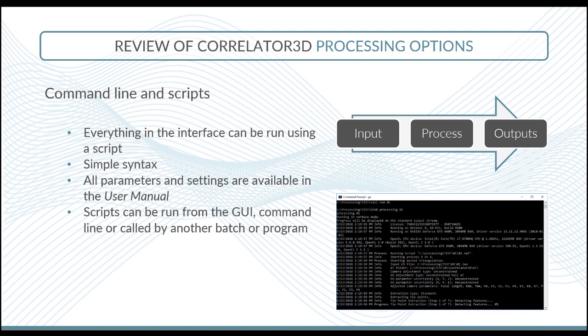So this makes a very powerful option for you if you want to highly automate your process and your workflow. All that you have in the software can be scripted, so you can really automate everything, even the small tools like change detection or the DEM inspection for checking the quality of your DEM. All of this can be automated with a script.